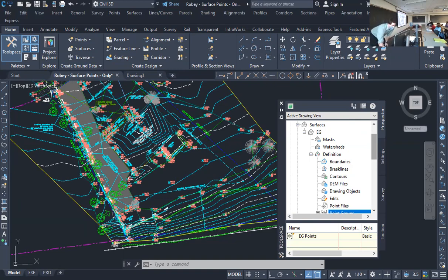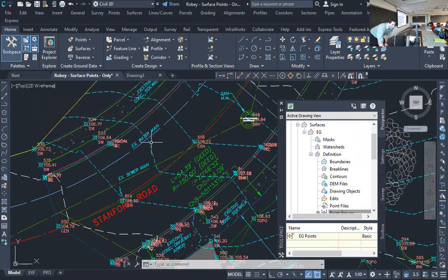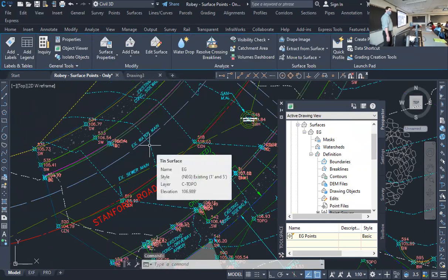Let's go up here and look at the road. I know there's a curb, right? So if I know there's a curb there, the contour should follow that curb for at least a little bit. It's not doing it. That's the importance of feature lines. You remember when we looked at the 3 different maps that we looked at before, where you add feature lines? That's the purpose of it. It's like a break in the contour. So how do you get those? Those are exactly what I just said, feature lines.